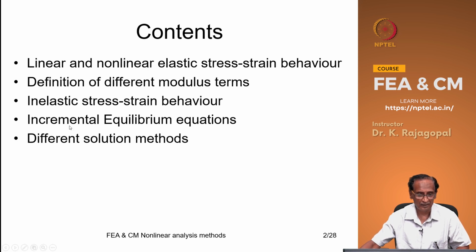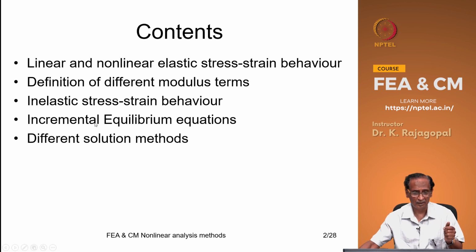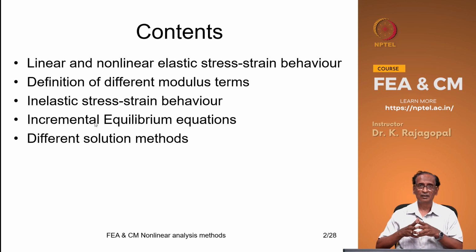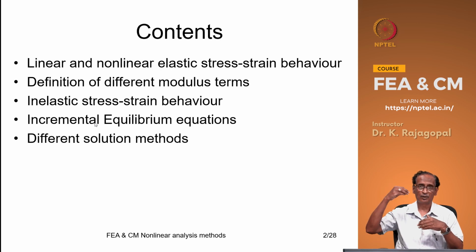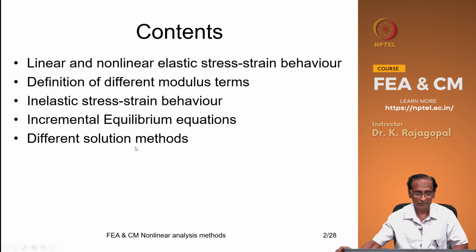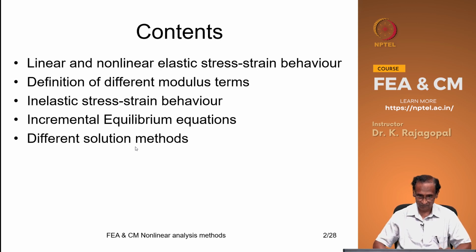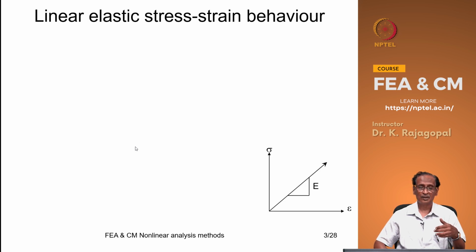And most importantly, we are going to rewrite our equilibrium equations in an incremental form, not in terms of the total stress form, but in an incremental form, and we have to write them such that we can maintain the equilibrium between the applied forces and then the reactions under all types of loading conditions, whether it is a construction induced loading or execution induced loading and so on. And then we will also look at the different solution methods. Some may be very expensive, some may be very fast and so on.